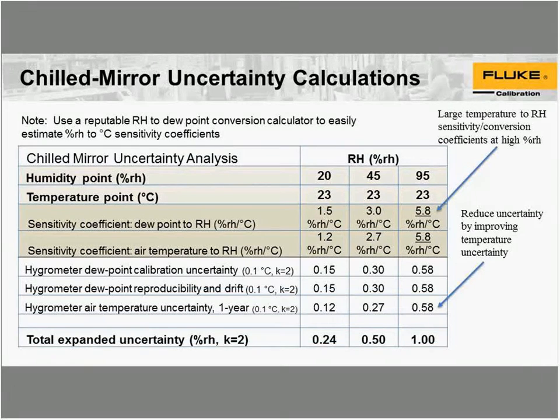But carefully though, because I'm trying to set an expectation that in the humidity world, especially at high humidities, the uncertainties can grow quite a bit, just basically because of the sensitivity of temperature as it relates to humidity. So hopefully you'll get a copy of this table so you can look at this and absorb it a little more. Now, if you don't know what the sensitivity coefficients are for your own calculations, don't worry.